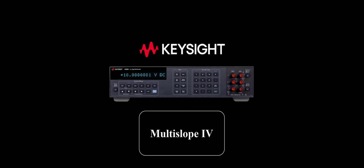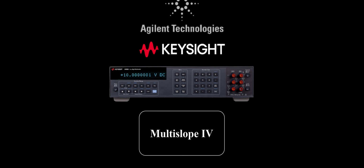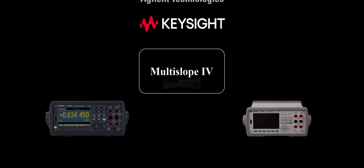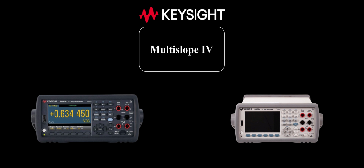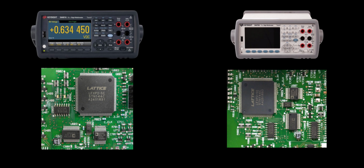What's next? We have now established that Multislope 4 is the future of precision ADC design, but the topmost of the line, the 3458A, still uses a simple Multislope 3 style run-up and Multislope rundown. I bet Keysight, who inherited the 3458A design from Agilent, who inherited it from HP, didn't dare to touch a nearly perfect existing design and couldn't be bothered to invest in modernization. However, most modern bench DMMs from Keysight, who probably own the Agilent patent, seem to follow the Multislope 4 recipe, like the 34461A and the high-end 34470A, both having the giveaway combination of fine and coarse ADCs.